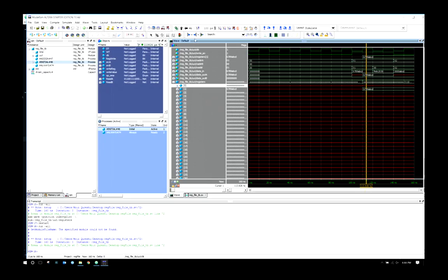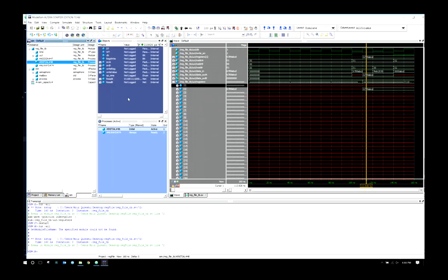So that's what ModelSim does, is you want to run tests for everything: your reg file, your program counter, your ALU. For your instruction ROM and program counter, you want to see if you're incrementing the program counter correctly depending on the flags you're giving, to see if you're branching correctly, see if the program counter changes up or down if you're branching backwards or forwards. So you want to test all those things.